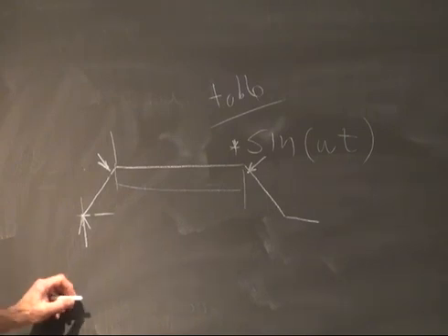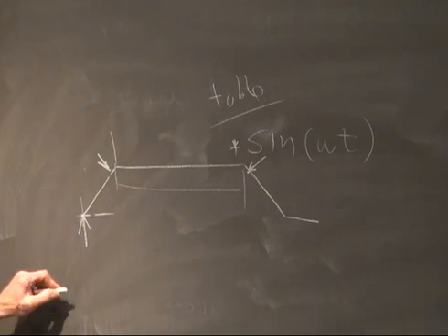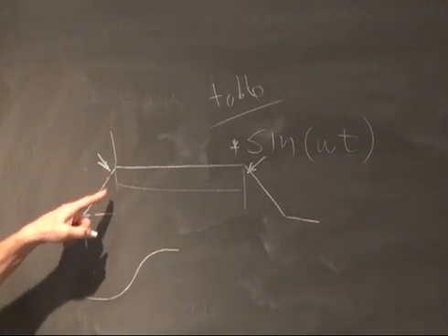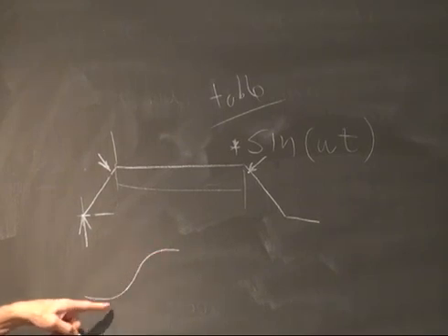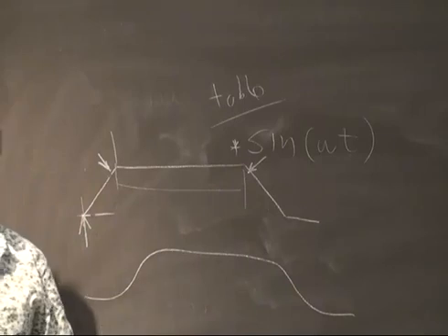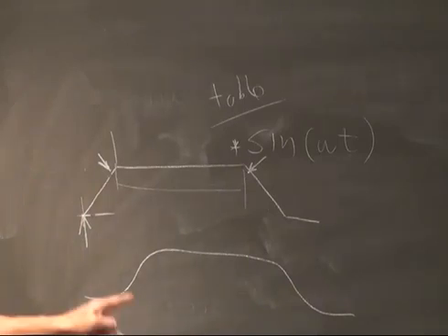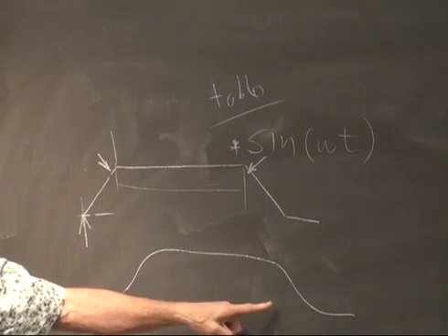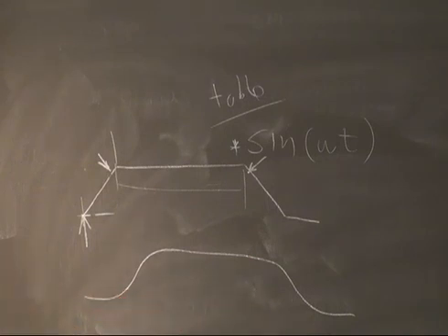If you want to make the spectral purity even better, you can get rid of all of the discontinuities in the first, second, and third derivatives by making this a raised cosine. And then you will need to do a table lookup to get the cosine values at the beginning and end. So the benefit of the cosine ramp is that there are fewer sharp changes.